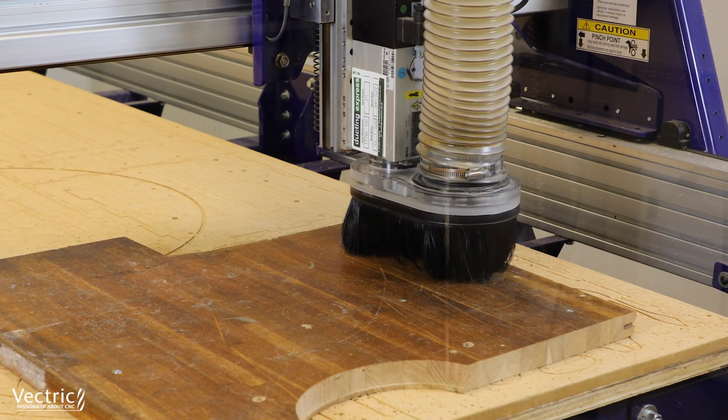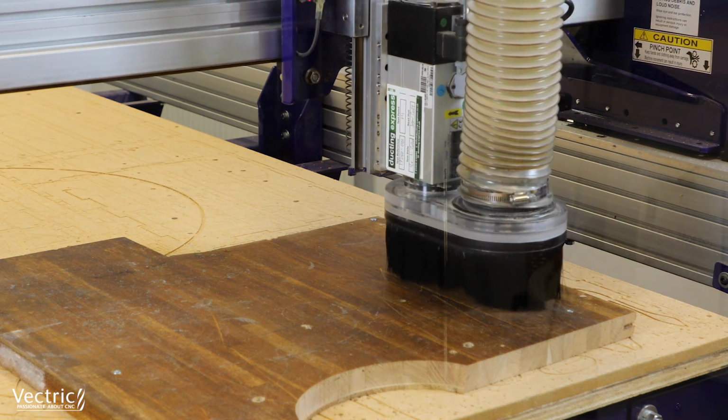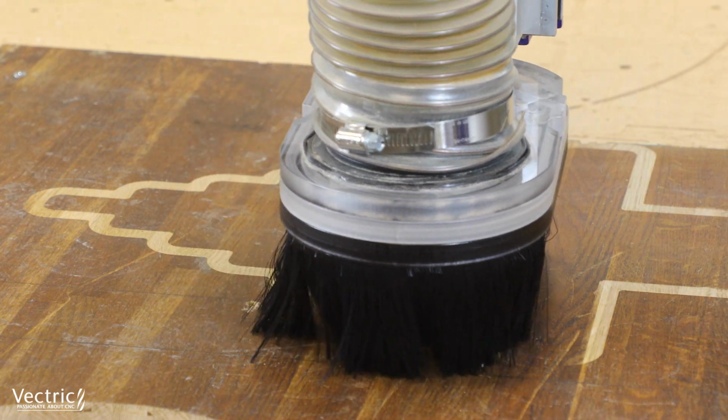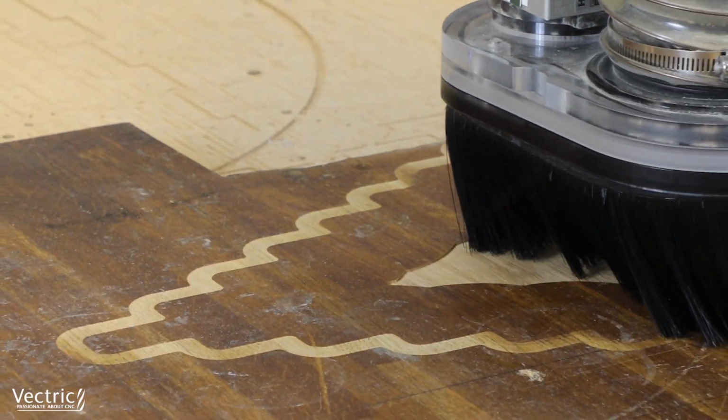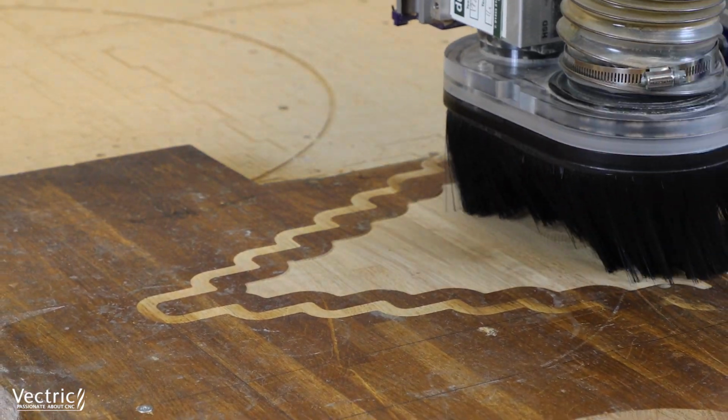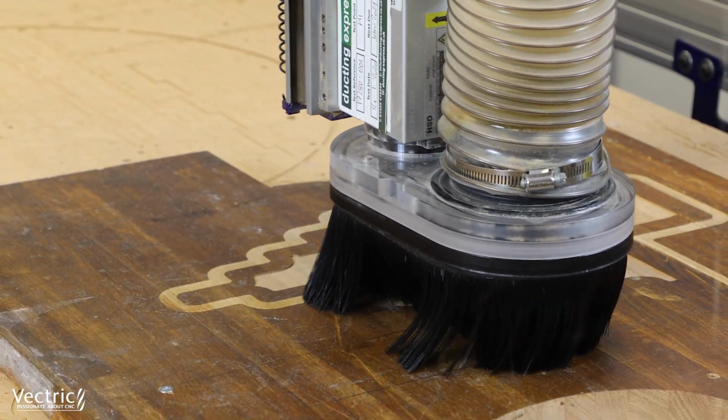This end mill we use for all of these tool paths except for the acrylic one. So this is going to go around and clean up the top edge of the actual maze, but you'll see that it missed a spot on the bottom right. That's because the material wasn't quite flat, so I had to do a bit of sanding a bit later.